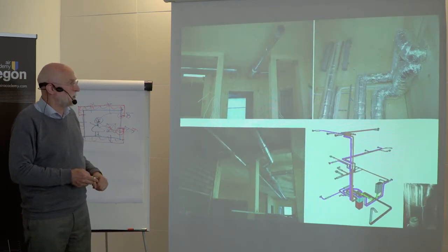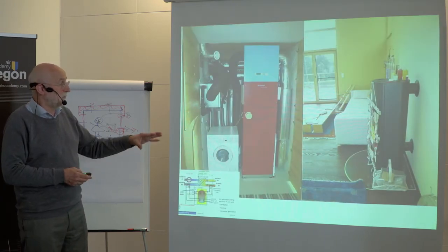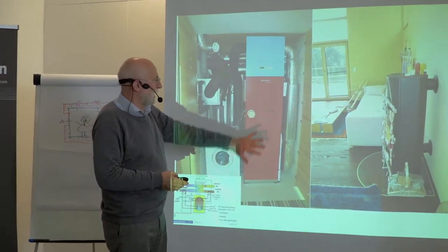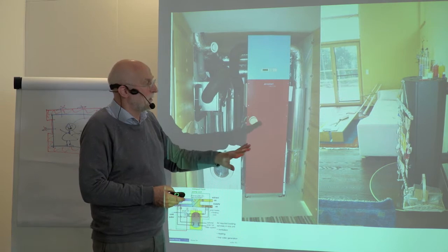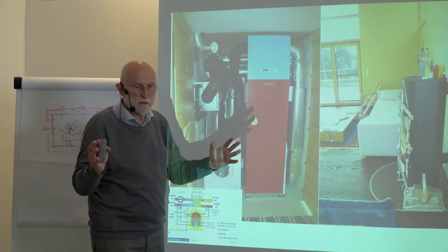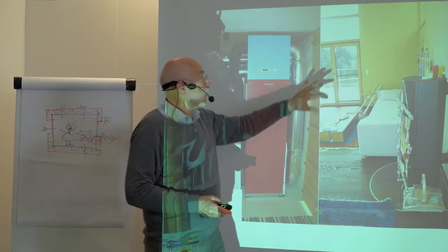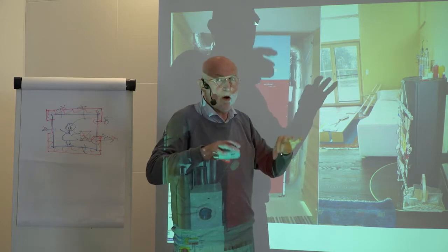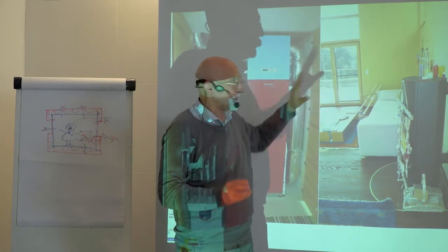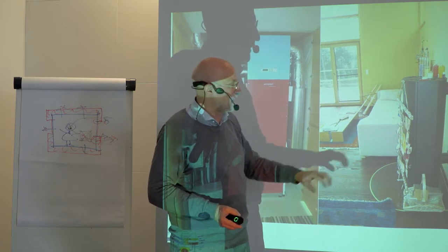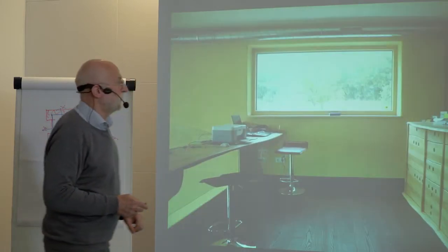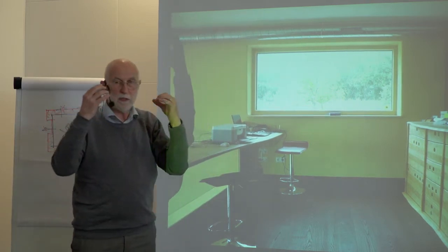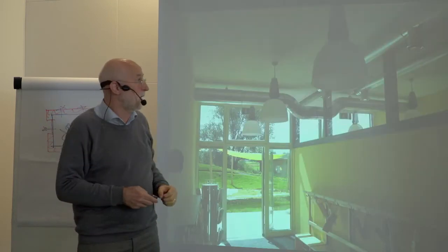Or in one-family houses, here we have no heating system. It's a heat pump inside the ventilation system, and therefore it can cover, if we have a passive house standard, all the heating demand. Since we have a very big screen here, in the morning the heat load, not the heat demand, can be higher than this 10 watt, which we can cover with air, and therefore they have a small stove. All the air ducts are open, because it's a concept that we should understand how our house is functioning.